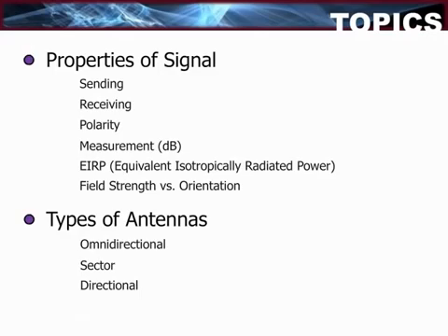The dB scale is logarithmic. We will use some simple tools to better understand how this scale works. EIRP, or equivalent isotropically radiated power, is a quantity of RF systems that typically comes into play when considering laws pertaining to the transmit power of radio transceivers.